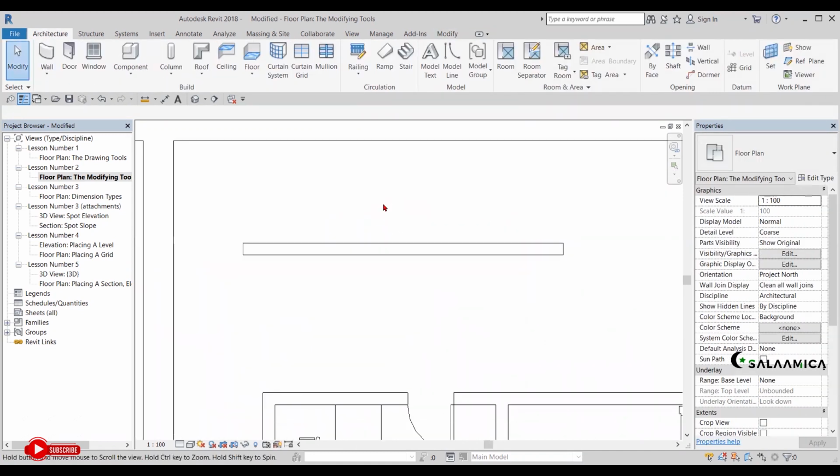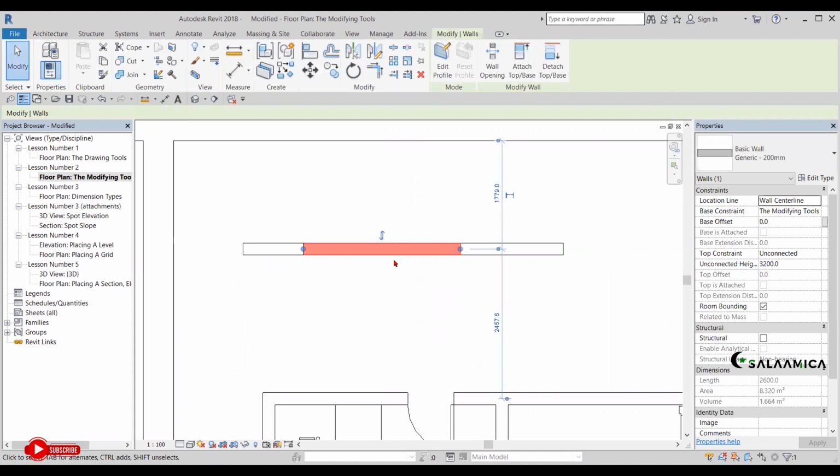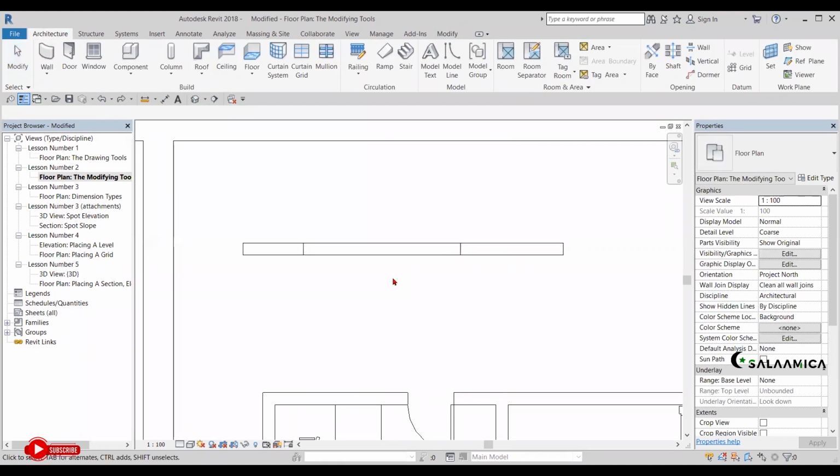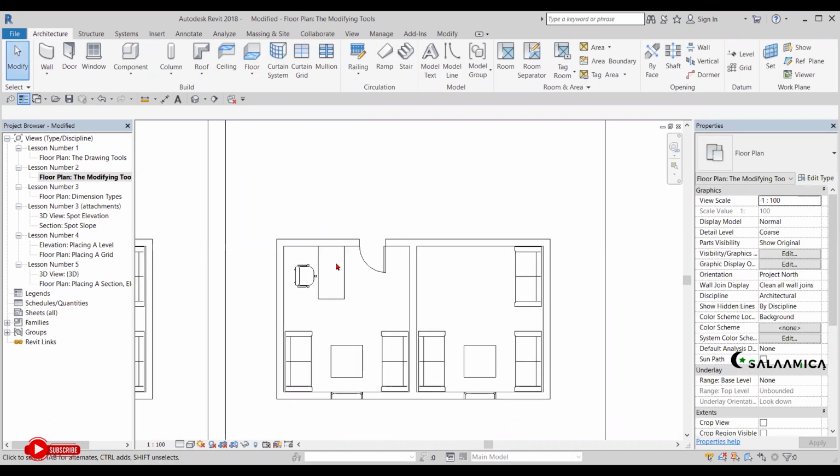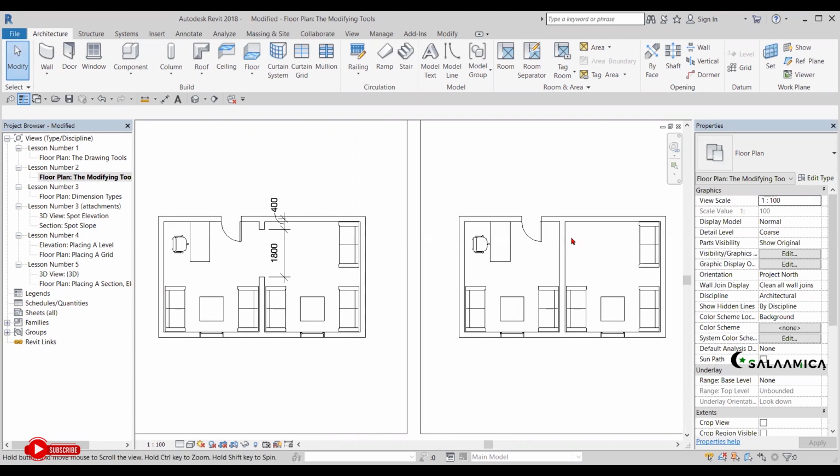Don't just watch here. So SL, if the delete inner segment is not checked, this is what will happen. I'll cut here, and then this portion will stay, and then we delete it. Now, if I press SL and I check this delete inner segment, if I click here, watch, if I click here, see, automatically this portion will be deleted. So that's exactly what we want to happen for this one. So when you press SL, make this delete inner segment checked.